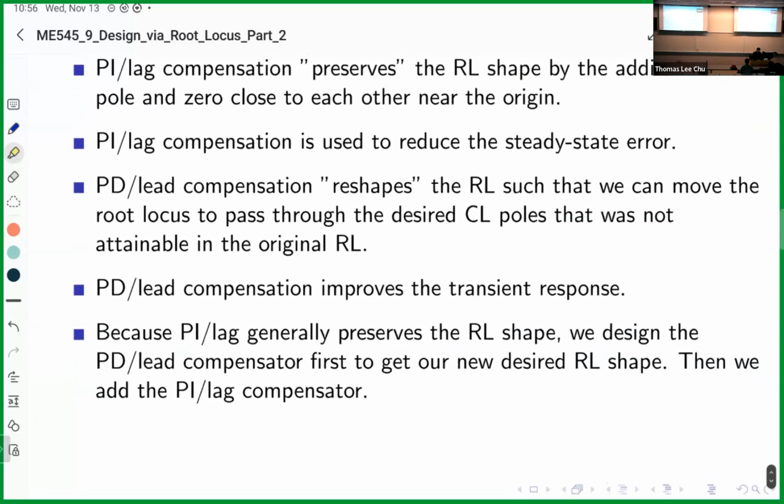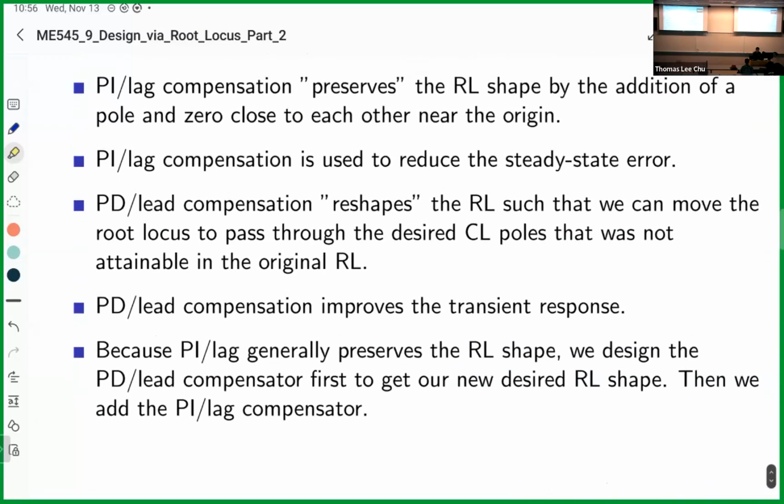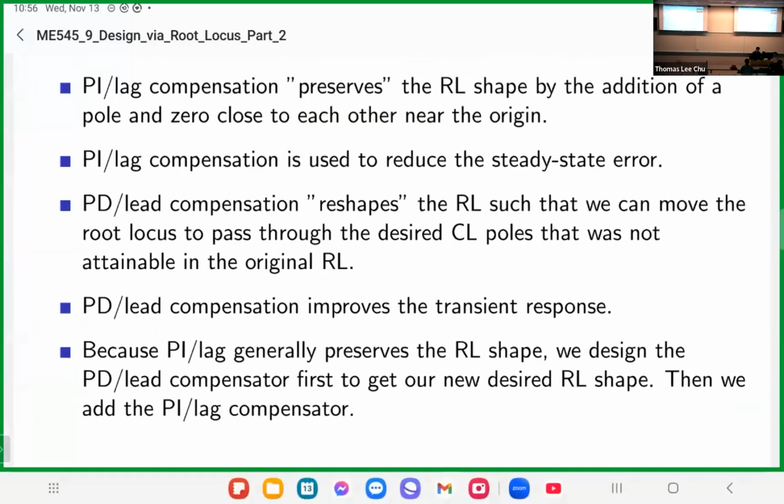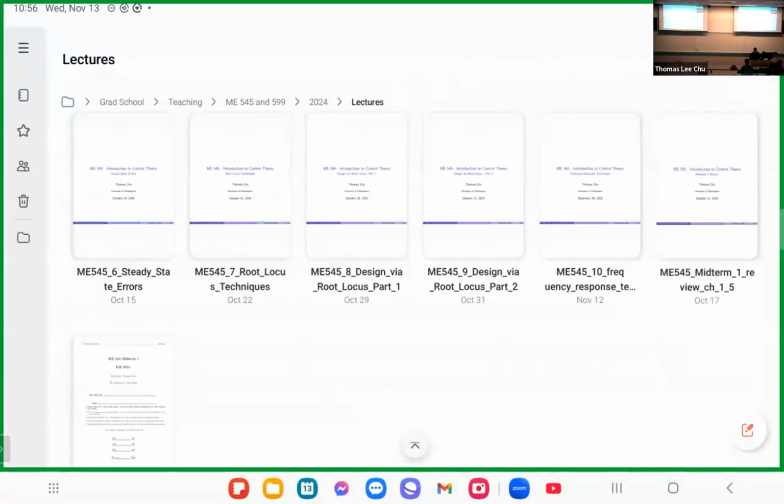One last thing I should probably write on here is that all of the design here is based off of a second order approximation, but it is not necessarily correct. If you use stepinfo, which you might have seen from homework, what you got from stepinfo and what you calculated is different, and that is also okay. All right, so I'm going to jump to chapter 10 after a quick demo.